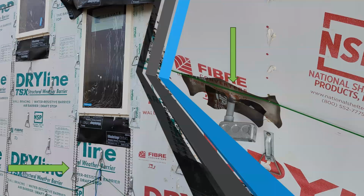This is kind of an example. Here's what we're seeing being installed as an air barrier. It's T-ply. In this case, there's OSB, there's Zip boards, but they all have seams and joints, and all those seams and joints need to be taped, and any penetrations through the air barrier must also be sealed. On the right is a product called Stretch Tape made by Zip. I'm not trying to promote any of their products, but this is what I saw when I was out walking a job site. It's an adhesive tape that can be stretched to create an airtight, waterproof seal. As you can see, it's pretty stretched, it's pretty thin, it's transparent in some places where they stretched it.